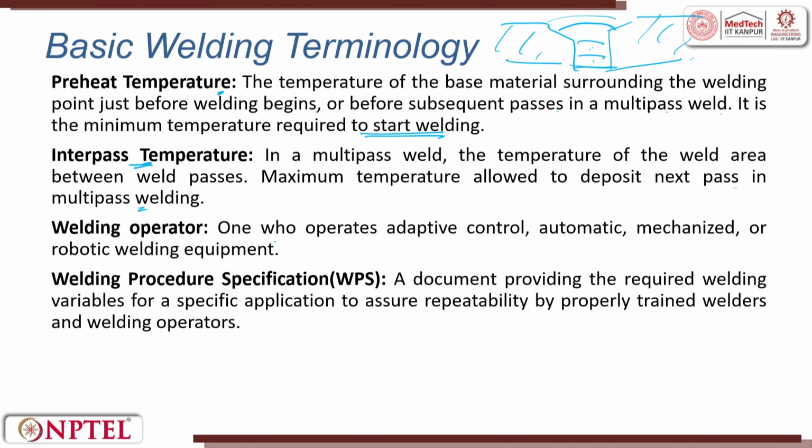The welding operator, one who operates the adaptive control automatic mechanized welding machine, is called a weld operator. A welding procedure specification is a document providing the required welding variables for a specified application to assure repeatability and reliability of the process. These are all done before the process starts.